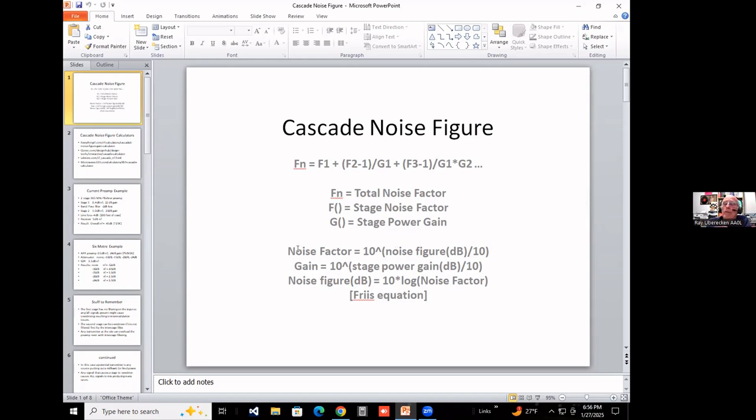So that's converting decibels in your head to the numerical equivalent factor. You only have to remember two numbers: 3 dB is equal to a factor of 2, and 10 dB is equal to a factor of 10. Then you can figure out everything from there in your head, but we'll go over that some other time.